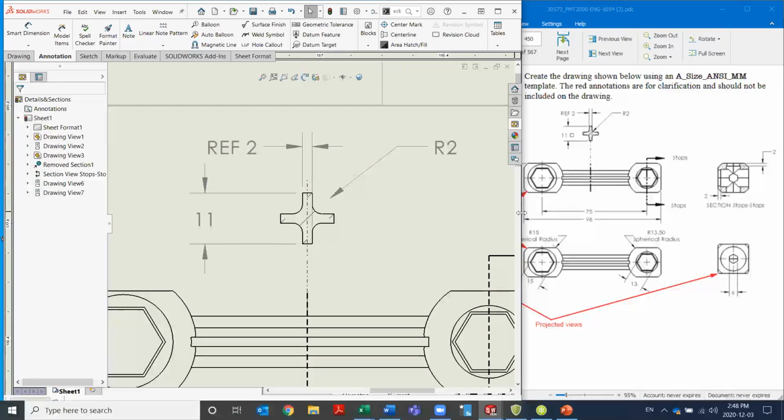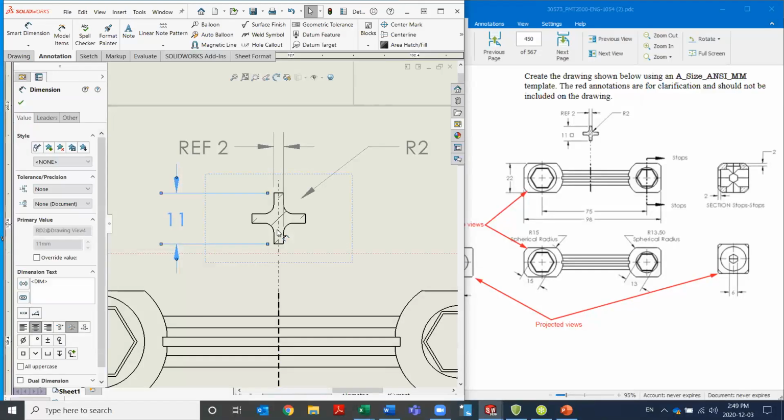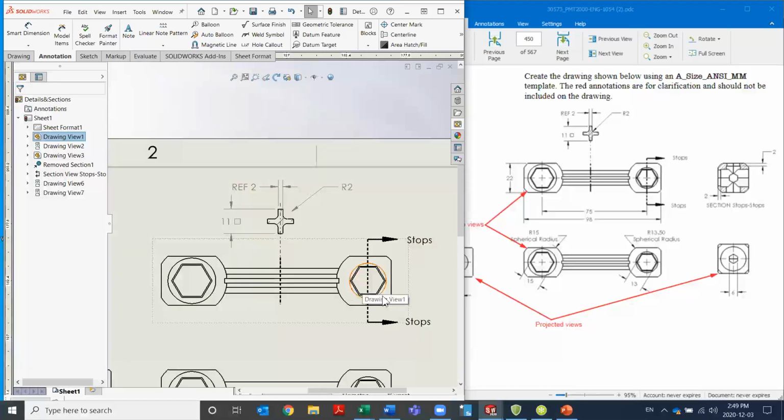One other thing you may notice here is we've got this weird symbol. It almost looks like this is supposed to be 110 millimeters. It's actually a square symbol that we've got there. If I click on this dimension, what I can see down here is a number of easy symbols we can add. We can even add more, but these are the common ones, and there's square right there. If I want to add it after the 110, I'm just going to bring my cursor to after the dimension code there, which is bringing in the dimension, and add in that square. It's as easy as that, nice and simple. And there we've got our dimensions on there.